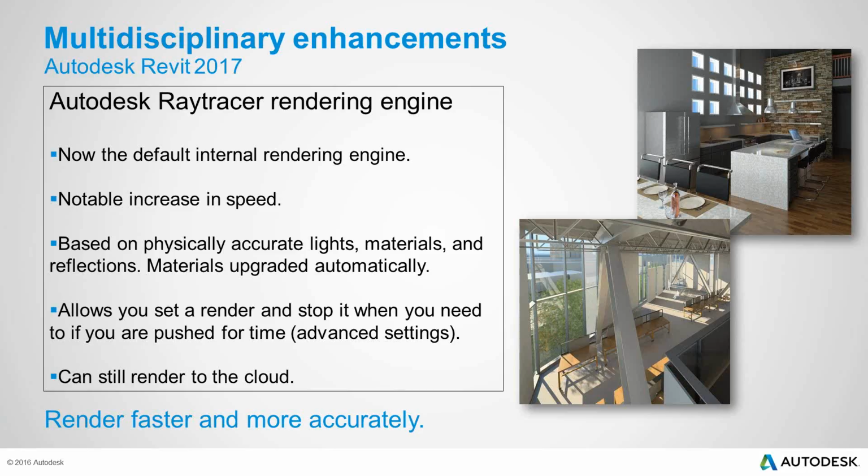One of the good things about it is that it's almost a recreation of the real way that light actually works inside a physical environment. So in Mental Ray, especially if it was an internal render, you'd have to use certain tools to try and create extra light inside. Then you'd have to sit there and wait until it rendered each little part of the window. If you didn't let it get right the way through to the end, then basically what it was producing was quite useless.